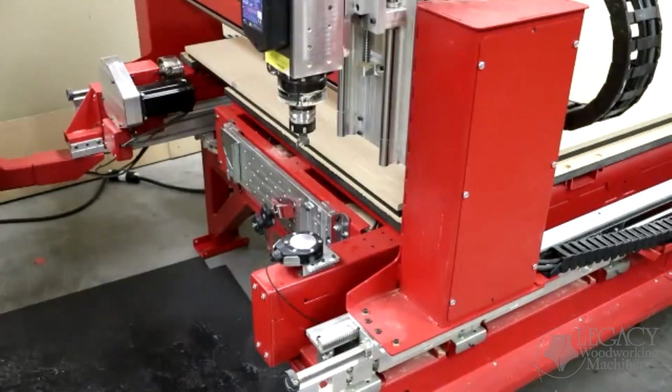So if you raised it 1/8 of an inch and this ran right over, you'd be right even with the surface of that table. So whatever the difference is between the material that it's sitting on and the top of the Smart Tool pad in this position, that measurement is recorded and kept. Smart Tool is turned on, and now you just run your program. That's the standard way to do it all the time. Right? And if you do it that way, you'll never be wrong.